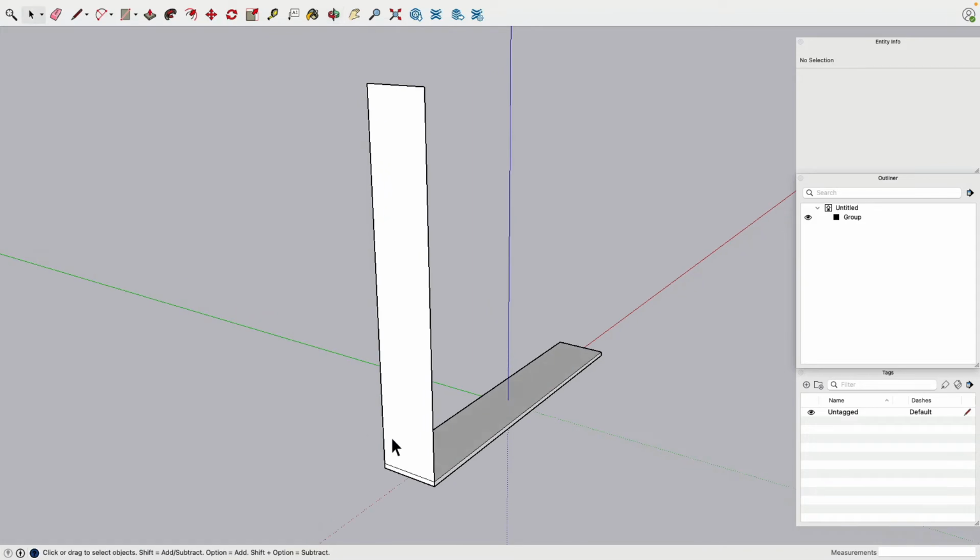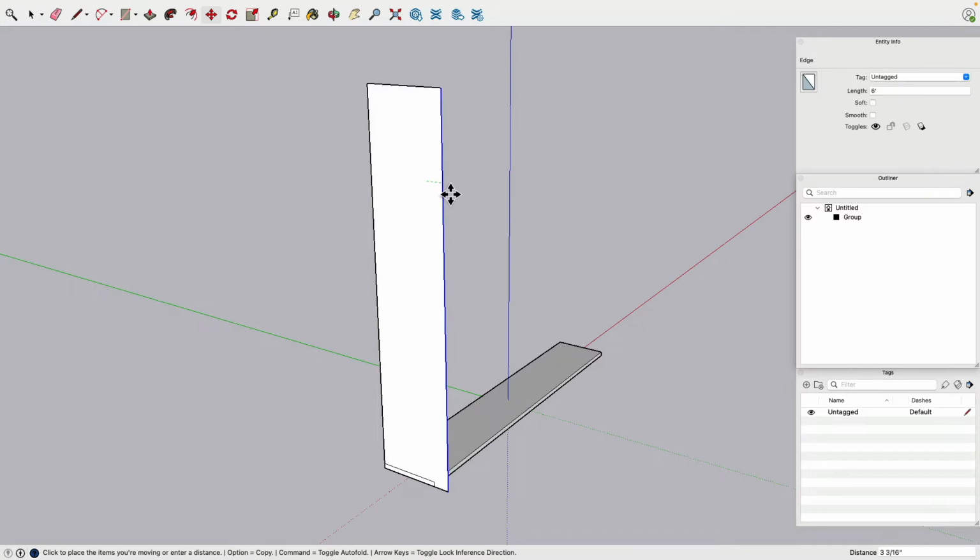Now we have a rectangle that defines the height, but not really the width. So if this board should sit inside this frame, this is already the opening. So this frame is not wide enough. We can select an edge, move, and then move this along the y-axis. But you see here, be careful with how you move the mouse.